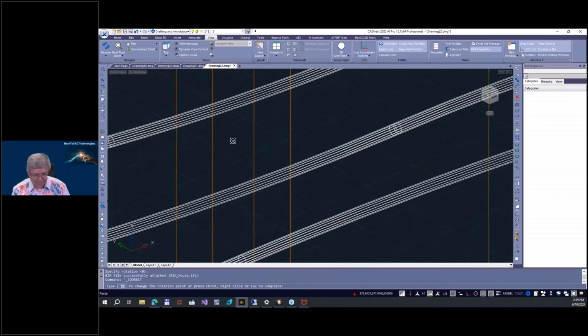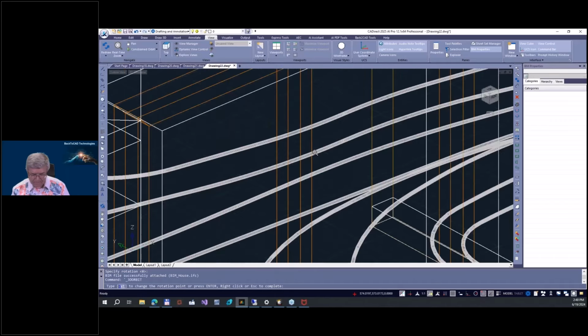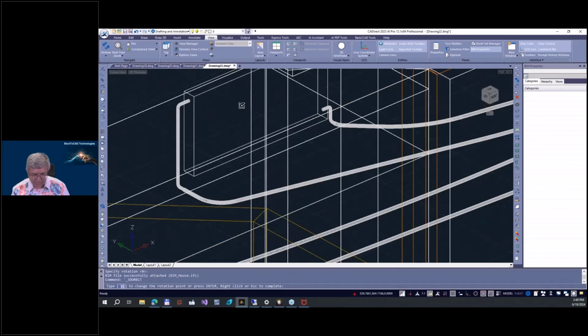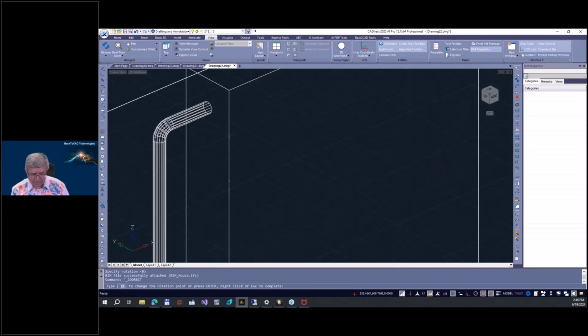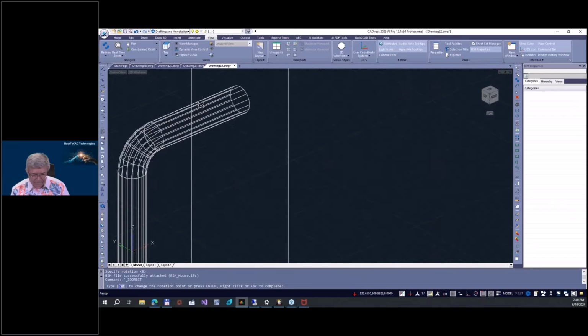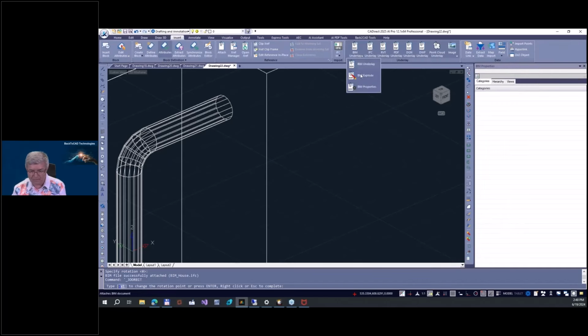Look, you can see the pipes here. How many elements are here? These are the duct pipes from, no, this is not duct pipes. These are the pipes for heaters. You can see this will produce a lot of elements. So I tell you, never try to explode this one using this insert beam underlay explode, because you will get a huge DWG drawing.